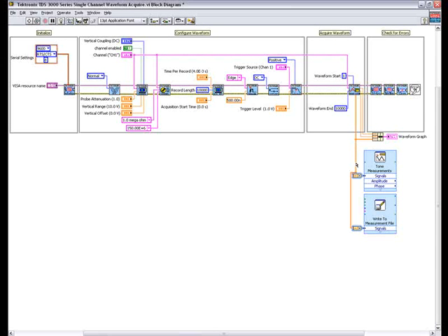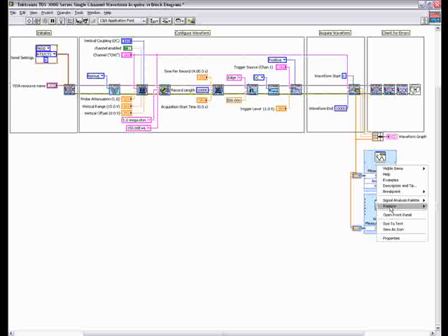You may be wondering what these functions are that LabVIEW placed on the block diagram when I wired my data to my Express VIs. These are called Convert to Dynamic Data functions. Express VIs have their own dynamic data type. LabVIEW, by default, places this function on the block diagram when an Express VI is wired to a non-Express VI to perform this conversion for you. To maintain proper programming practices, I will wire error clusters through my Express VIs. I can also right-click on my VIs and choose View as Icon to make them appear smaller on my block diagram.